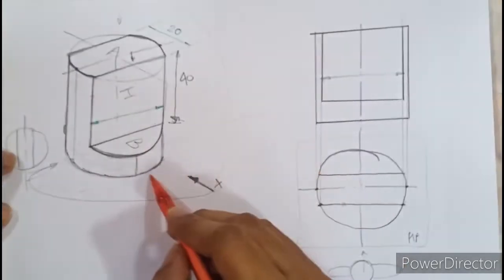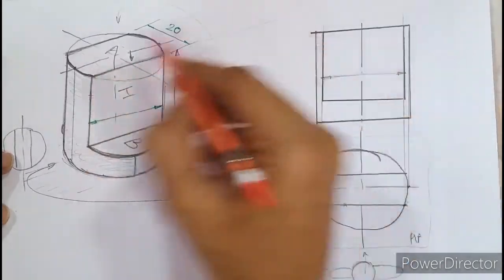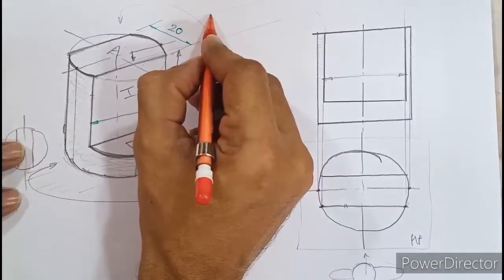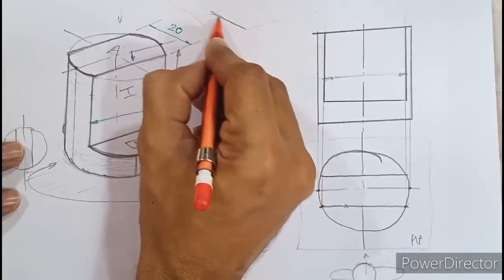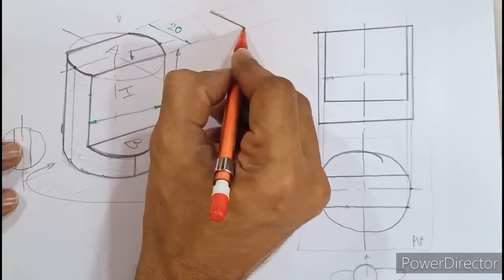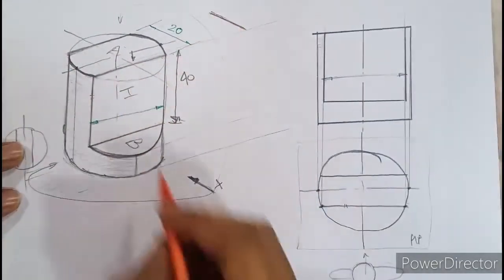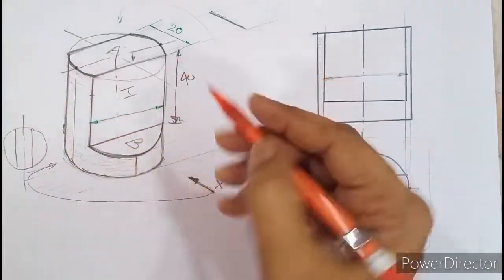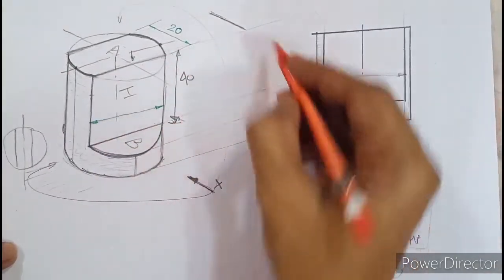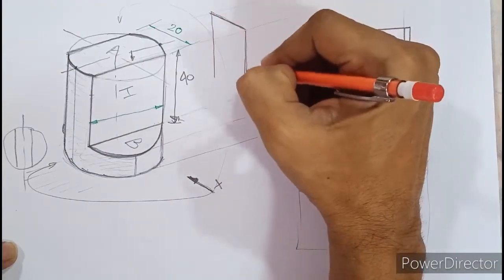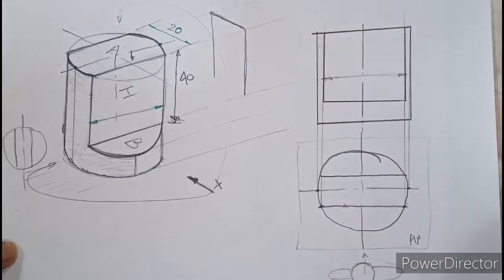So when you project this and draw the side view of this surface, I think it will look like a T shape. Let us see one by one. This horizontal line I have drawn is the top circular edge, which will be seen as a line, isn't it? Then these 2 vertical edges till here. Both the vertical edges will be seen as vertical lines.